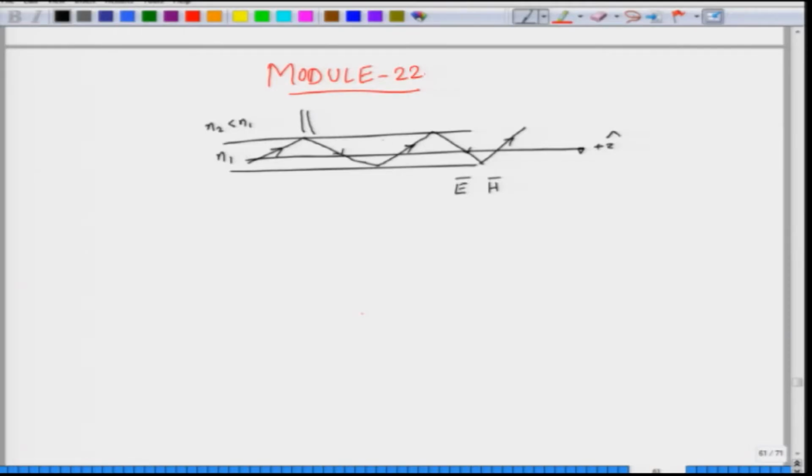Now, before we study the propagation in this slab waveguide, let me point out that this slab, in the case of an integrated optical circuit, is usually made out of substrates which are silica or other types of substrate. For example, it could be lithium niobate, and you do not actually get only a slab, you get a multi-layer structure, but propagation usually happens in only one layer. The other layers are there for many different reasons, but you try to make light confined into one particular channel or one particular waveguide layer itself. So, I am simplifying the problem, I do not want to deal with many layers.